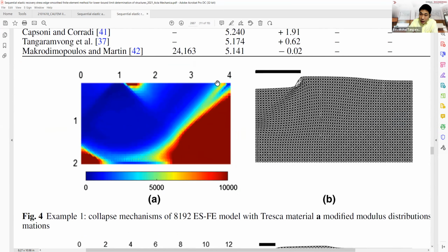As I showed you before, the nice thing is that the more you discretize the mesh, the smoother the distribution of the displacement and the stresses. This is the von Mises stress, and it shows the behavior of the stress transfer. We have the foundation with uniform pressure applied, right? I just model it as half of the punch problem. So this is the boundary of the structure you're looking at. I take only half of it, so the loading will be somewhere that I put my hand on.